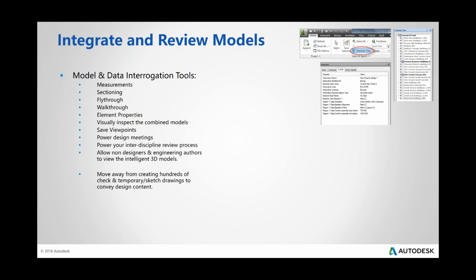So next, obviously, there's the properties tab. Again, probably one of the more critical elements that I was talking about before. Once an element's been selected, this is where all those properties or attributes and really the design intent and information about those elements has been attached, and this is where you'll view that. As I said, this is probably one of the most important tools as it allows you to understand the design intent and critical information about that element, so helping the decision-making process.